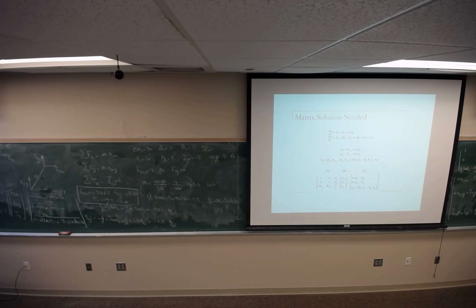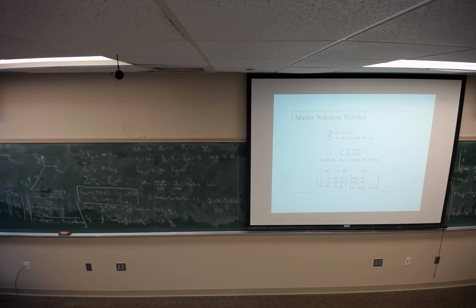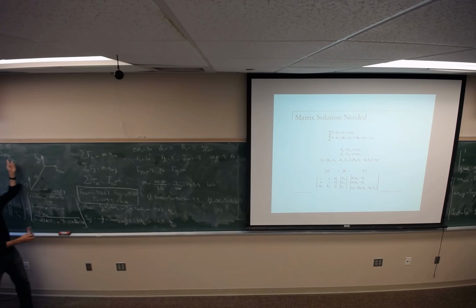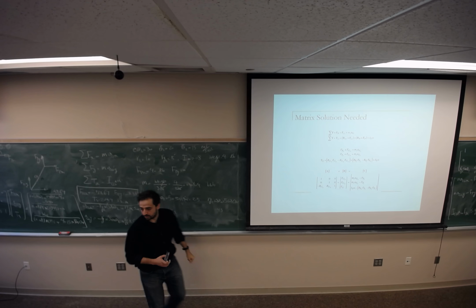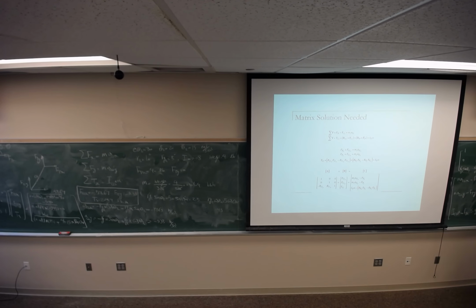Any question about this? I just wanted to show you the steps for one link which has pure rotation. Now if I connect link 3 and link 4, you have a 4-bar mechanism. I can rewrite these equations for 3 moving links, get 9 equations, 9 by 9, 9 variables, and a 9 by 1 vector.